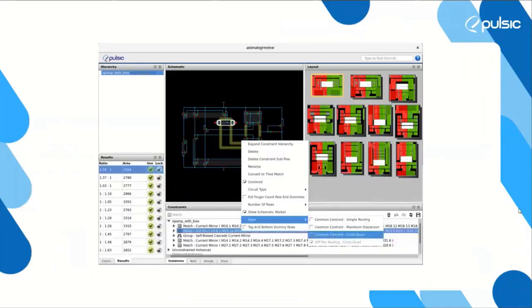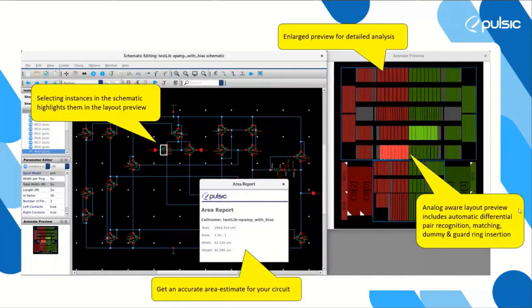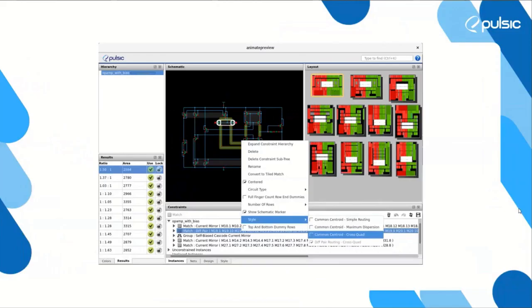So actually, I'm going to go back a slide here. The tool is actually using your PDK, your DRC rules. This is actual layout here. It's drawn slightly differently in this case, but it's really using the OpenAccess database and the P cells and the PDK and the DRC rules and making real layout in the background. You can zoom in, and this is the customization GUI.